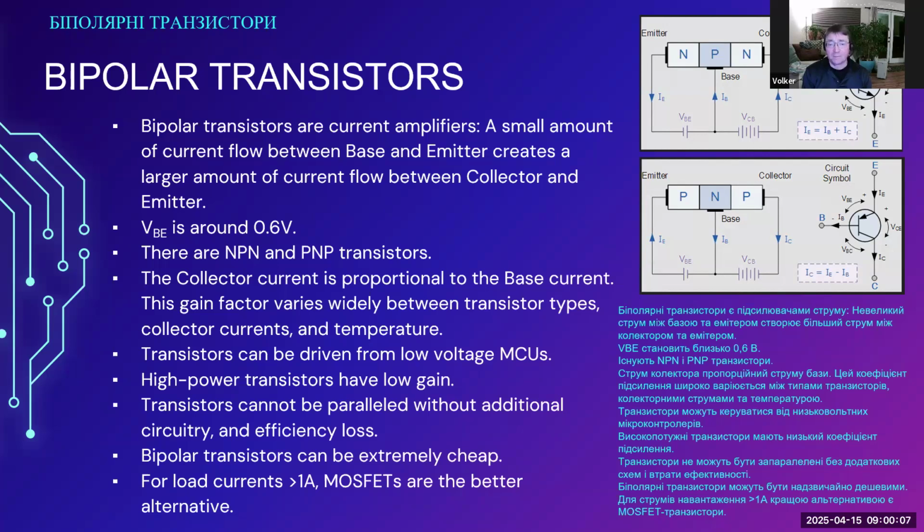This is not an unusual voltage, like all silicon PN junctions have this voltage. I'm putting it in here because what this means is that even very low power microcontrollers can switch bipolar junction transistors. The transistors are not obsolete, but they're old components. But they're still around. Most of the higher power transistors have been replaced by MOSFETs, and I'm going to talk about that.